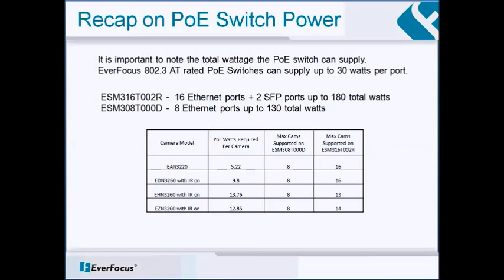As a recap from Level 1 training on PoE switch power, it is important to know the total wattage the PoE switch can supply. EverFocus 802.3at rated PoE switches can supply up to 30 watts per port. The 16-port version of the switch supplies 180 total watts. The 8-port version of the switch supports 130 total watts.